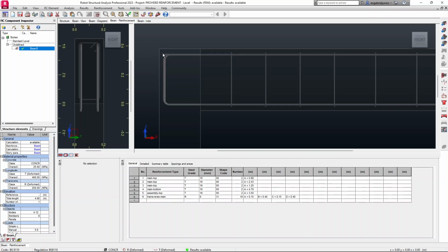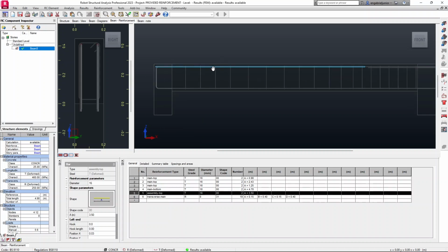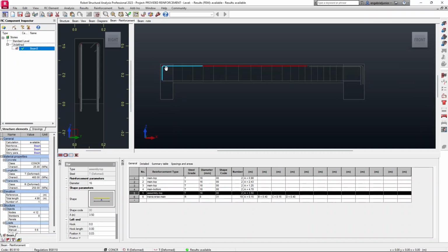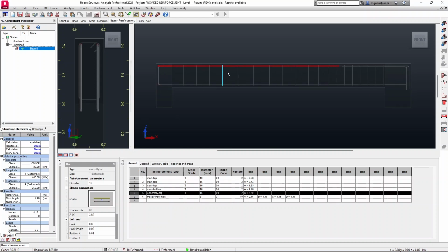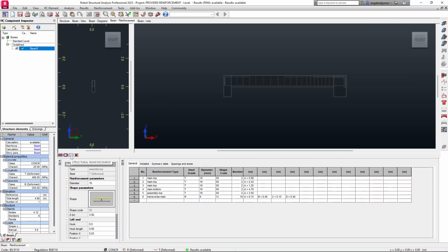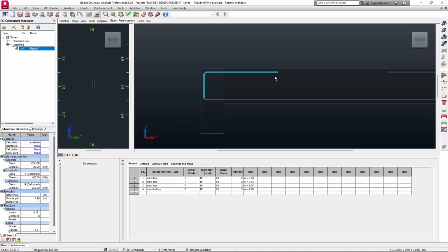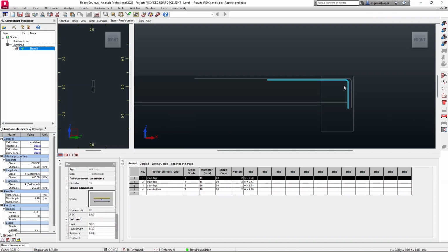And if I want to add hooks, perhaps on this bar here, that's an assembly bar. It's just a hanger bar. It doesn't really provide any resistance to moments. Then also you can filter out the different steel. For example, I can remove the structural reinforcement that is now for the hanger bars. As you can see, it's been removed. I can also, if I want to just view the longitudinal reinforcements, remove the transverse so that I can view only the main reinforcements, like that.